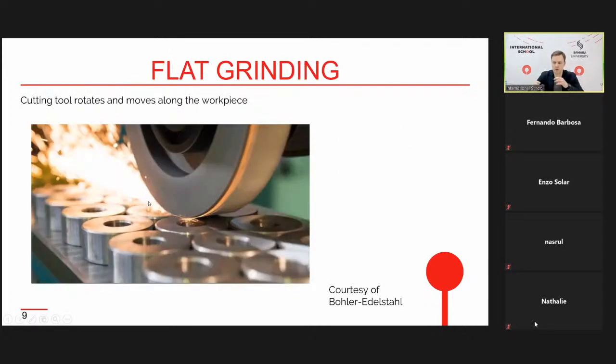But when we don't use cutting cooling fluids, we can see these particles as sparks after machining. So this is a real process, and without using cooling liquids, we can see these sparks. The temperature in grinding is very high. That's why the chip, after removing from the surface, has a high temperature. That's why we can see the chip as a number of sparks.